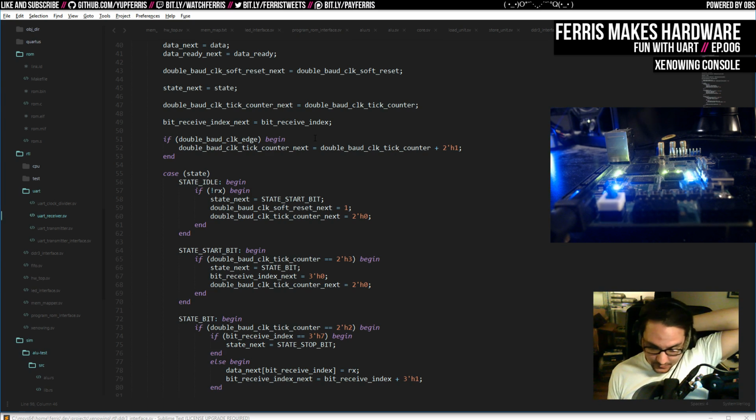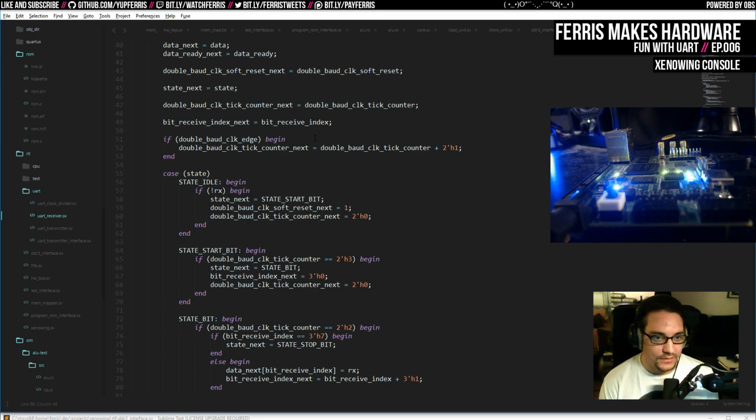We probably will have to implement some kind of protocol, because when I'm thinking about this, we need to tell the thing that the transmission ends. We don't want it to always send 64K every time, because that will actually take some time. In this case, it's going to be 9600 baud, which is about a kilobyte a second, and I don't want to wait a whole minute to reset the ROM and make sure this works. So I'd rather send smaller transmissions. So what I'm thinking I can do is have a very simple protocol for this.